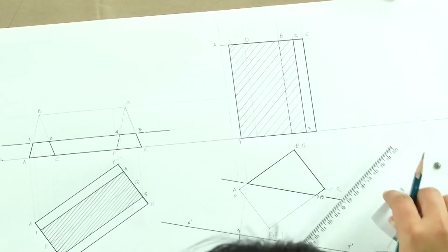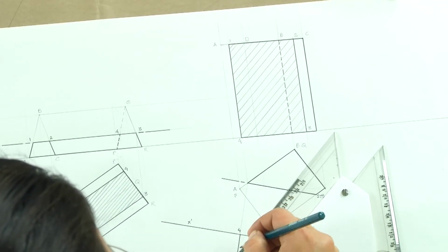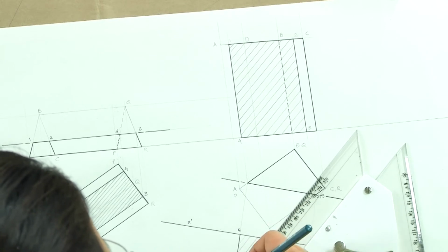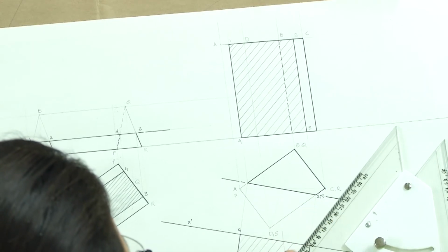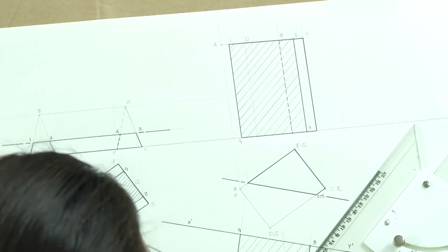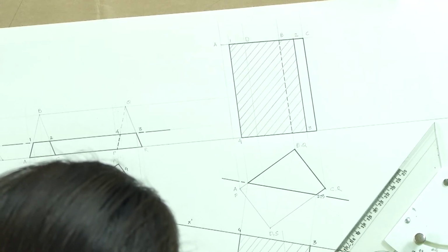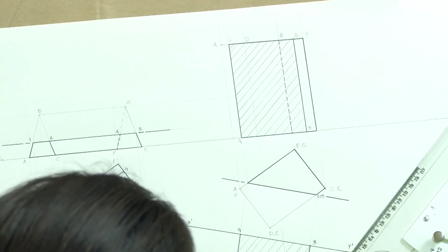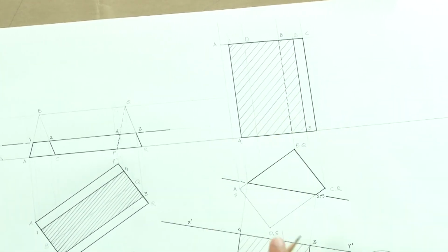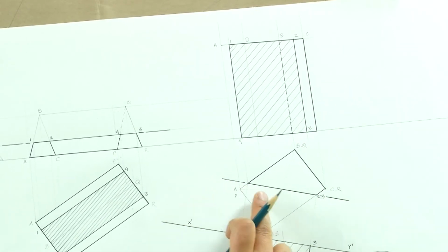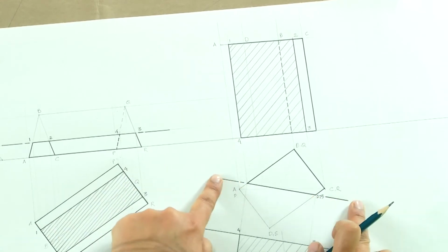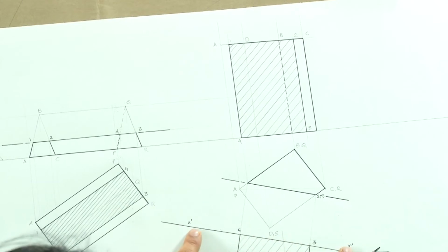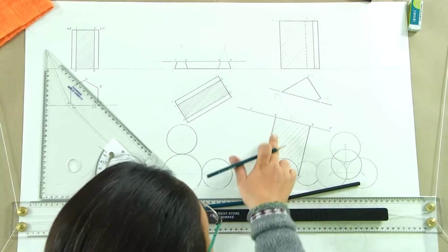And the true shape of the section will also be hatched here. So what we have here is this true shape of the section. So if you see again, we had the section as a rectangle, because in this case also this section plane is actually parallel to the axis, and that is why we are going to be seeing the section as a rectangle, and the true shape of the section will be drawn on a plane parallel to the section plane. So we will draw a new auxiliary plane and a new reference line X dash Y dash and project the true shape of the section onto this.